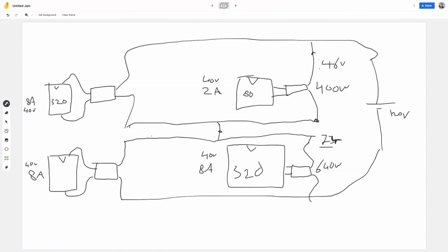They removed it. But to make sure it works, MPPTs don't work in series like this by default. You have to do some testing or validating with your manufacturer of the MPPTs, or make your own MPPTs to make it work. Even with the Nomura MPPTs, the ones that are intended for putting in series, I've done some measurements with them, and the intermediate volts get really unstable, and they interfere with each other. There's some control theory in your MPPT that you have to do well to make this work. Tokai managed to make it work last year with their buck boost converters that they put in series.